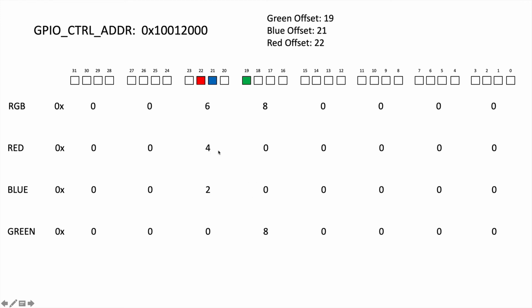They basically represent this bit field offset that's clearly outlined in the documentation. But connecting the dots from a GPIO offset, a pin number, into a register kind of gets confusing to put all of those dots together. So that's why I drew this picture to hopefully get you through and understand how the GPIO works. And with this information, now it's very easy for us to write assembly language code that can talk to the GPIO register, and we know exactly which pins or bit field we want to talk to. So each of the bits in the bit field represents a pin on the board.